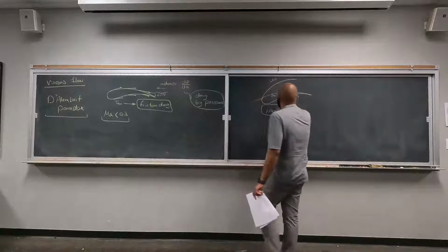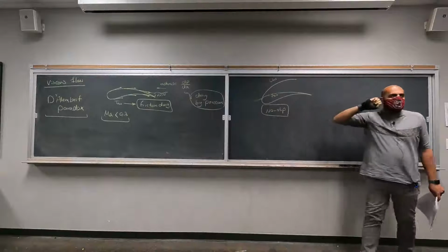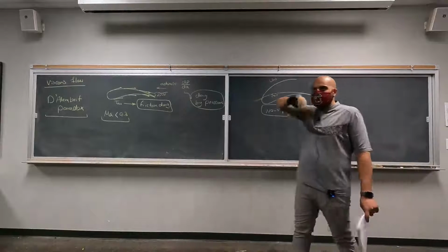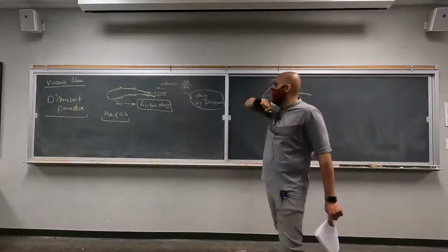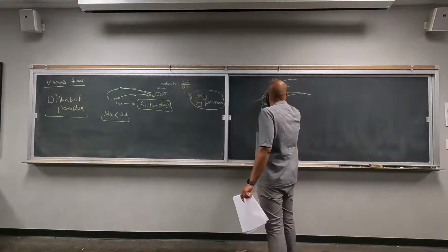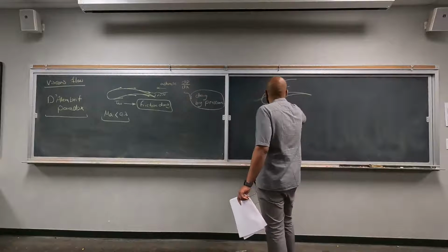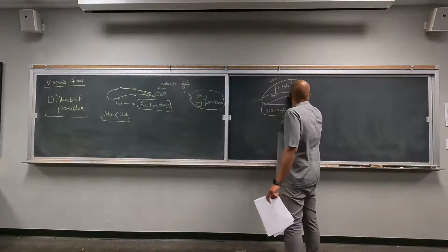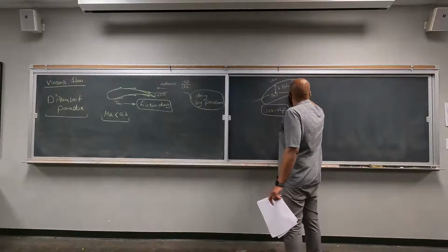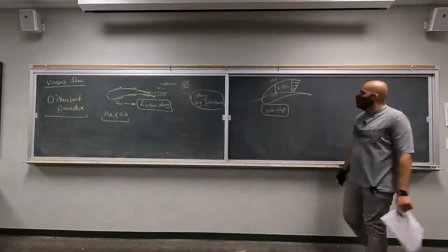This region in which we have a velocity gradient from 0 to u infinity, usually the limit is 99% of u infinity, is called the boundary layer. And its thickness is called delta. Very important parameter, when the velocity is changing from 0 to u infinity.